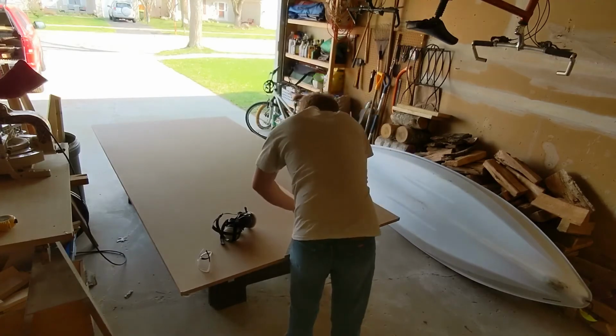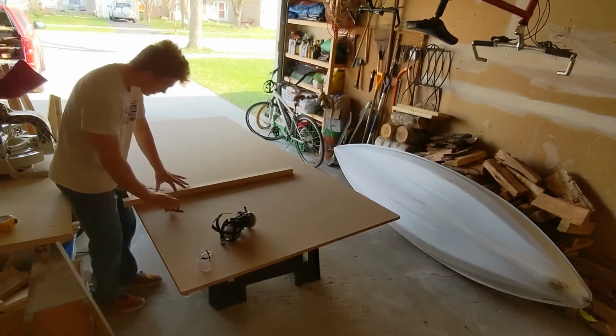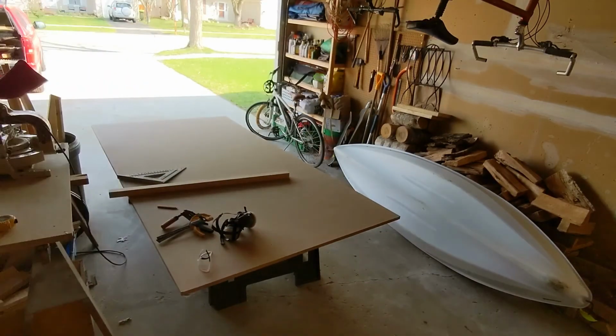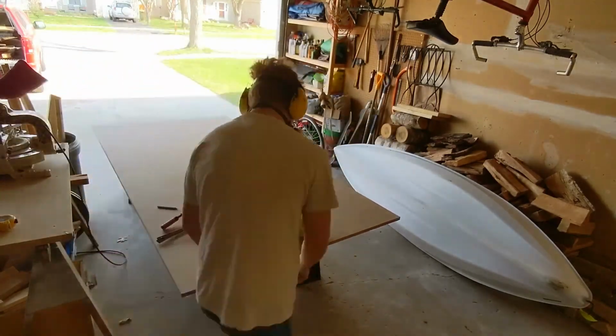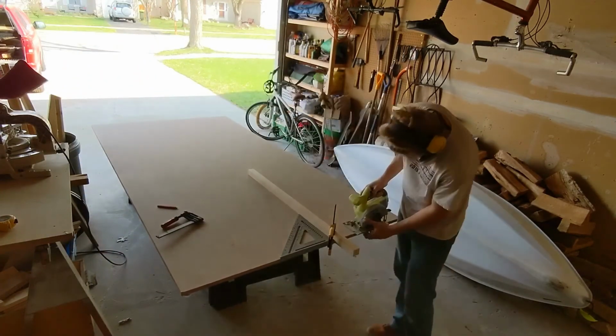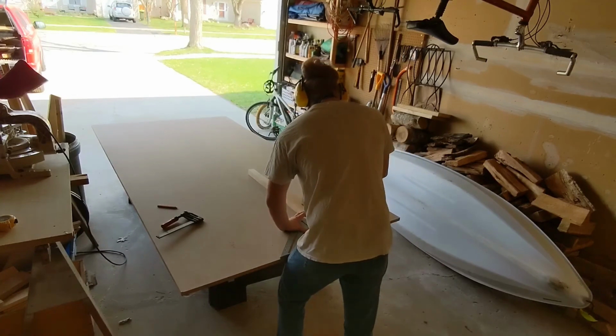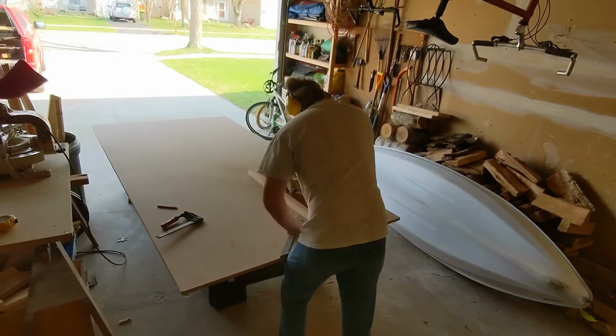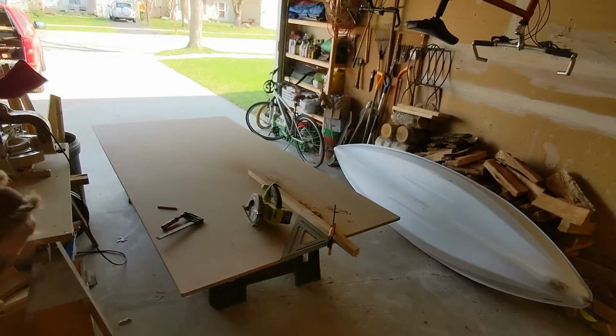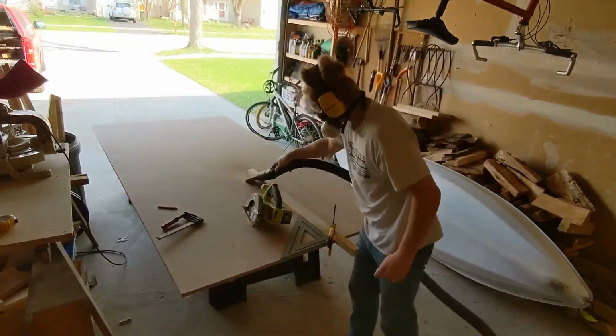Alrighty, so in this clip I'm cutting out the spoil board, which will be 32 by 32 as I mentioned previously. I'm going to lay this down on two pieces of MDF I just screwed down to my table as a temporary spoil board. I'm going to lay this down, secure it up, and then run the file.